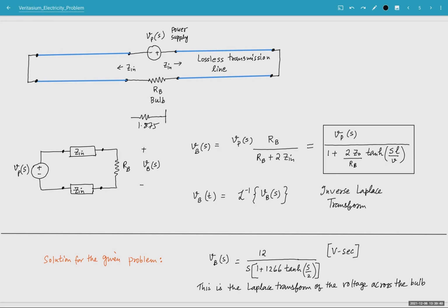One interesting thing that will happen is that the LEDs do not conduct any current, they appear almost open with very high impedance, unless the voltage across the diodes is in excess of the turn-on voltage. So when you put the LED bulb here, it will appear as an open circuit in the beginning.